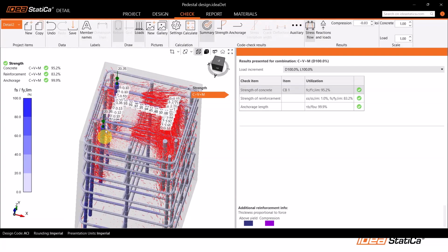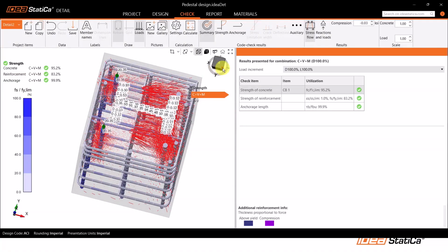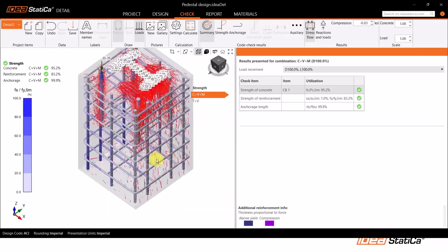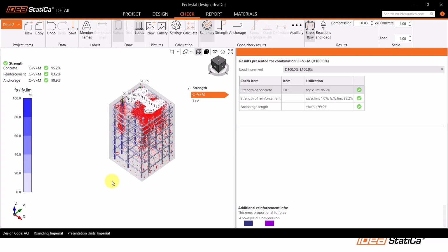That's helping out a lot for the tension forces on the anchors, right? Again, for this demonstration, I decided to do only the pedestal. But if we have the whole thing, like the isolated foundation as well, we can also review the development length and look into the anchorage results to see if that is enough for that development length, right?